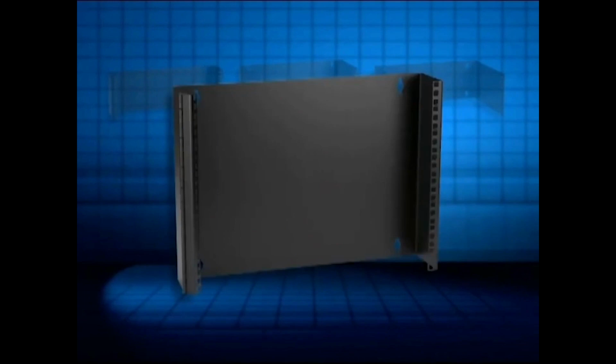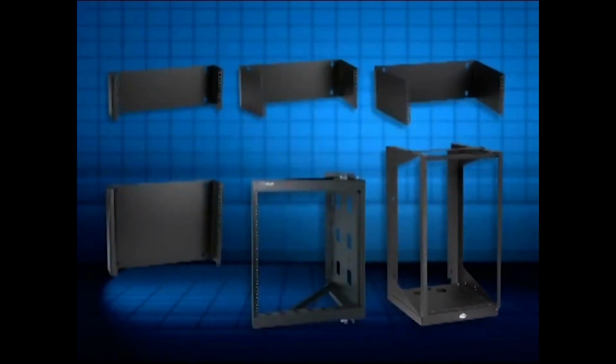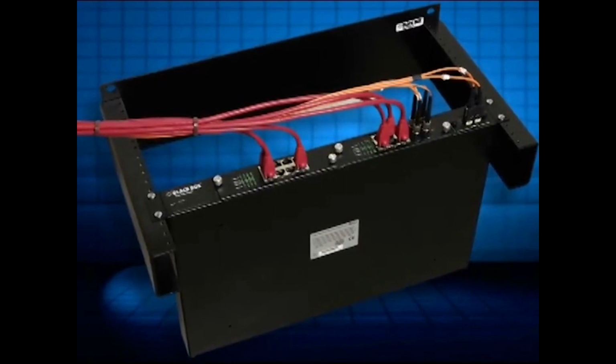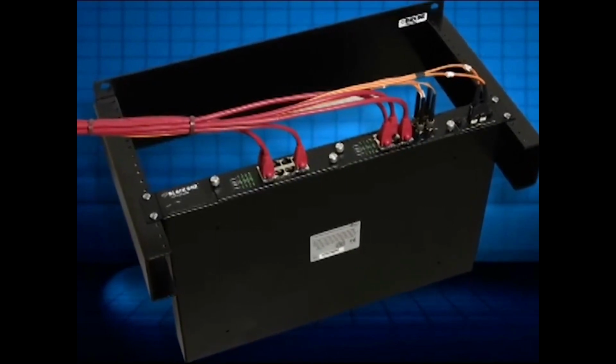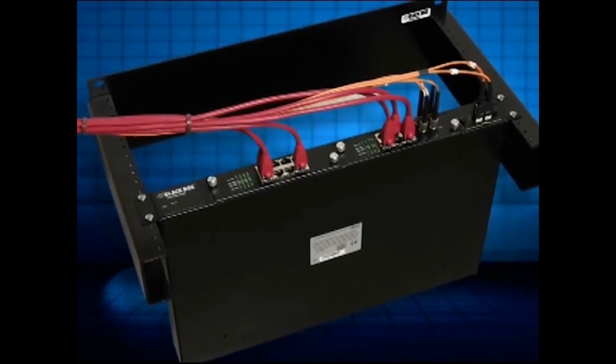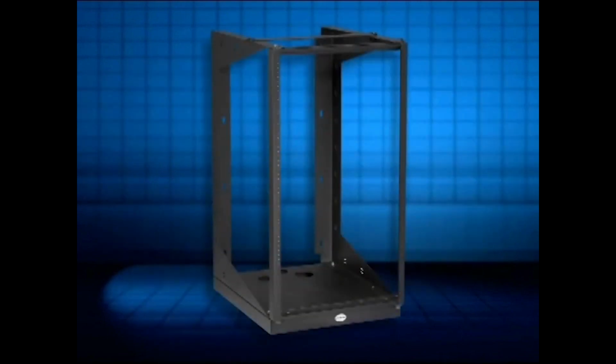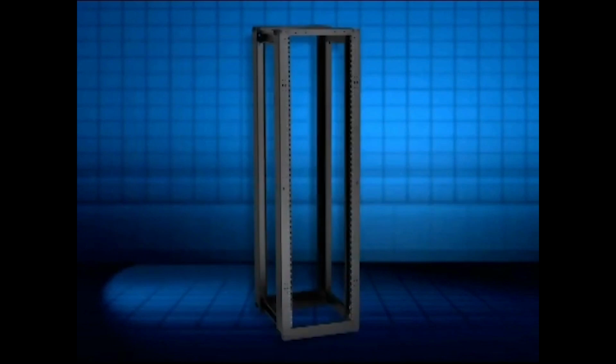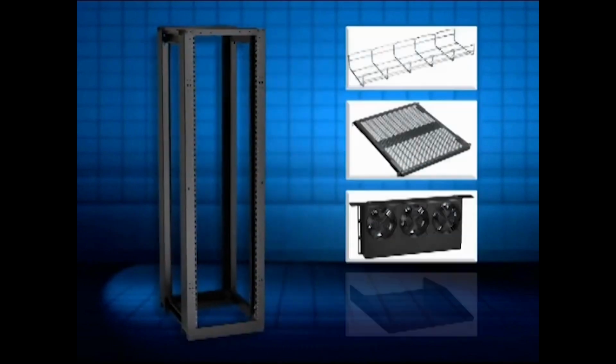These types of racks are very convenient for installing in cramped wiring closets or narrow hallways. Some even swing out for easy equipment installation and cable connections. Other low-profile racks enable you to flush mount equipment vertically against a wall to further reduce the amount of space they take up. Wall mount racks are typically designed to be installed on 16-inch on-center studs or on backing boards, which are then attached to the wall. Now that you have a rack chosen for your application, you need to select the appropriate accessories.